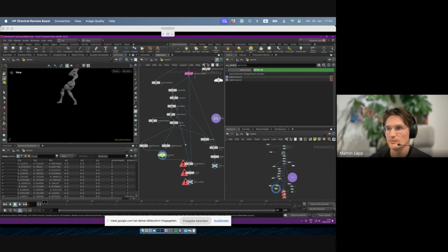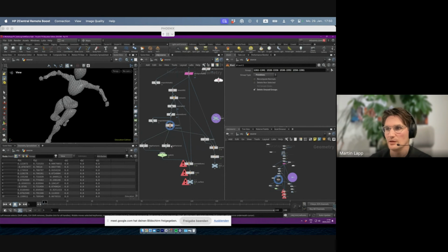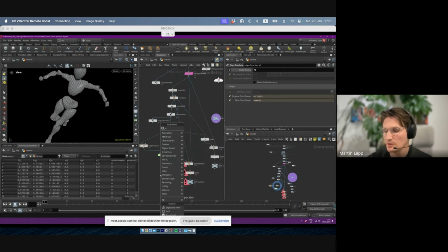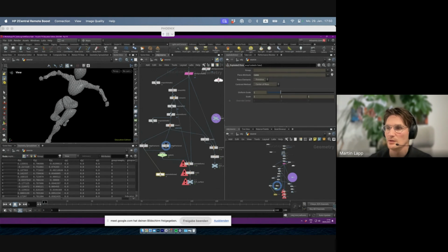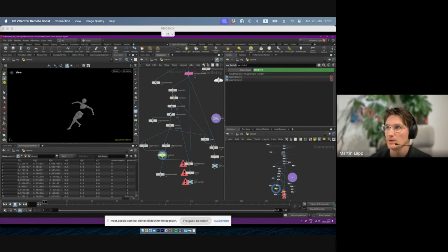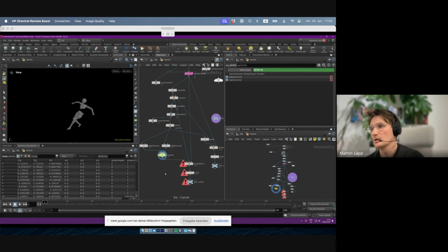So again, if I look at this guy, this is heavily changed geometry. At one time I'm using 240 pieces, and at another only 70 pieces. So if we drop down and explode the view, we can see that this guy has only so many pieces, and this guy has a lot more. Then I'm switching based on a modulus function, which is based on the frame. Basically it counts to 3, and at every 3, it switches between 1 and 0.